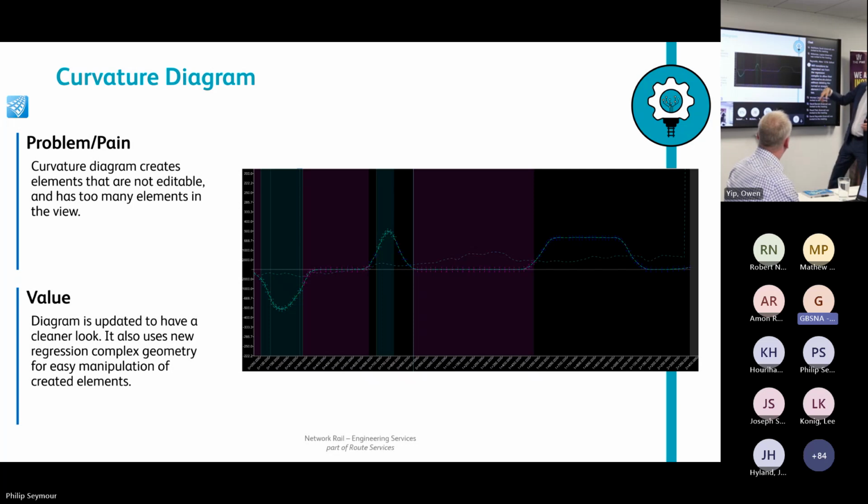Curvature, still there. We got rid of that. We had a thing called 1 over, what was it, deflection, which was really crazy. It's now back to radii. Pretty much the same box. We've got these zones still. You can still see the existing cant if you create from rails and stuff like that. But still use it. Keep it here. If I do stuff on plan using that previous trace, these are all highlighted here and it'll show me there. The colors mean it's a curve or a straight, stuff like that. Next one, Phil.